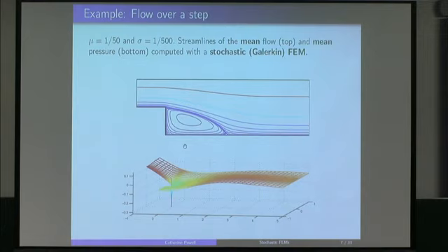So here I'm computing flow through a channel. This is called a backward-facing step problem. It's a sort of a classical toy problem. It's interesting because we get these recirculations in the flow, and we want to know about these quite accurately. Here you have an estimate of the expected pressure. And what can you see here? You can see there's this big spike here.